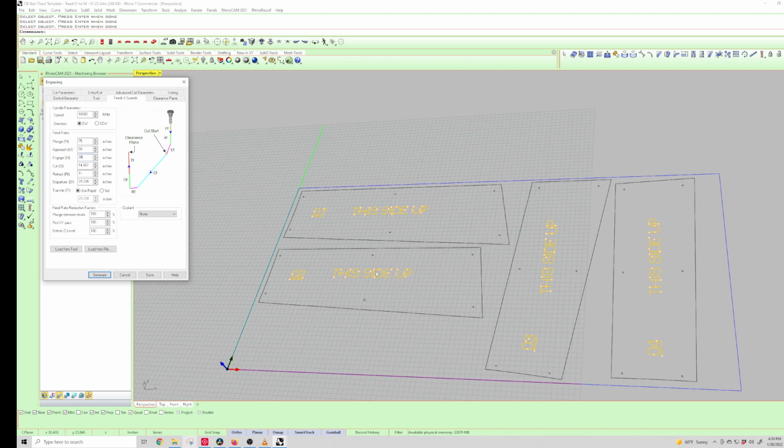I don't want to go too fast, so I'll probably put these guys at the 75 range also. You can mess with those based on how you feel it's cutting on the machine, and make the alterations based on how big your letters are, and how many smooth curves there are versus direct changes in X, Y, and Z, or the X and the Y. Retract 75.